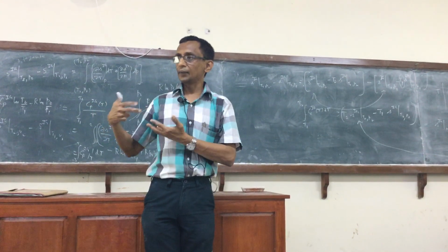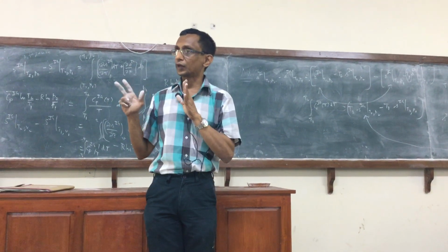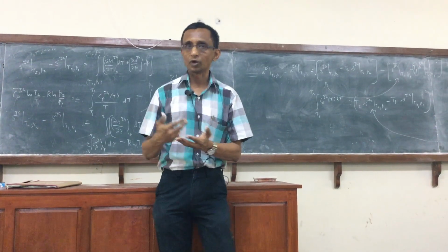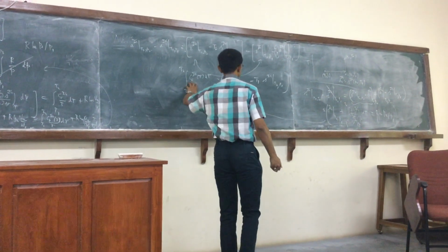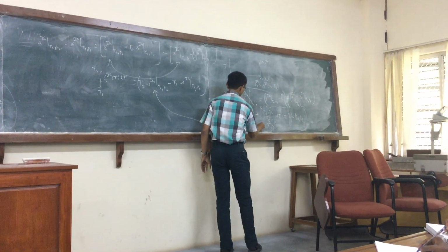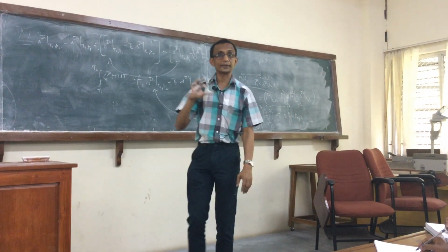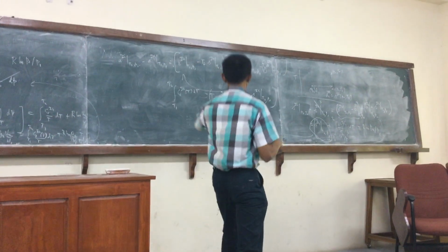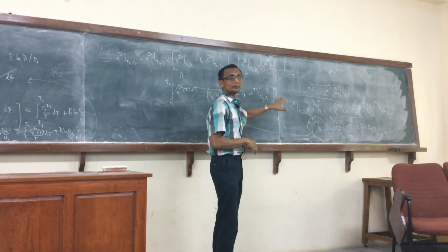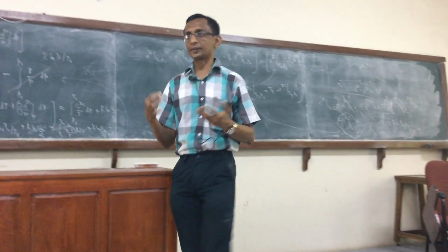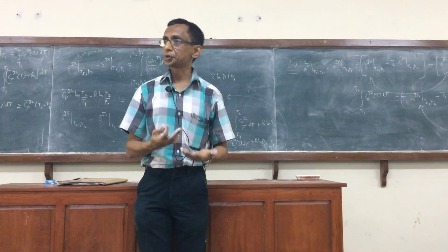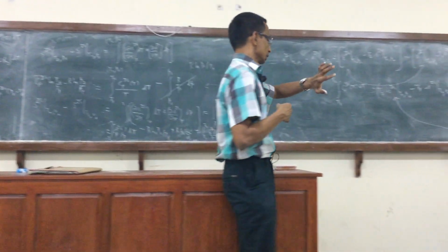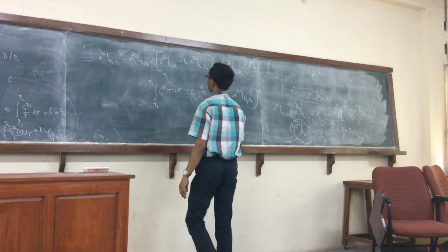And given T1 and P1, or at least the value of the entropy of the ideal gas for that substance at a particular temperature and pressure. So the whole formula, apart from Cp, will also depend on a particular value of the entropy of the ideal gas at T1, P1. I can sort of simplify and remove this dependence on both, because the two are related. Right? I'll maybe give it as an exercise, and you can easily find out what the final form would be.